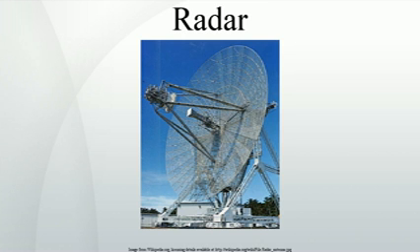Limiting factors. Beam path and range. The radar beam would follow a linear path in vacuum, but it really follows a somewhat curved path in the atmosphere because of the variation of the refractive index of air, that is called the radar horizon. Even when the beam is emitted parallel to the ground, it will rise above it as the Earth curvature sinks below the horizon. Furthermore, the signal is attenuated by the medium it crosses, and the beam disperses.